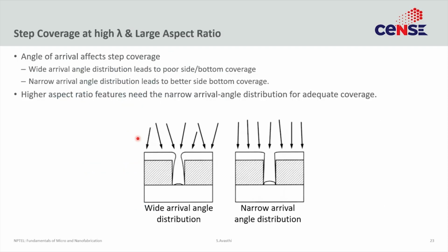Let's talk a little bit about step coverage. We discussed that CVD is often very good at step coverage because it's temperature driven, etc. But here there is no effect of temperature so much. Often the substrate is at room temperature. What you have to be careful about is the direction of the incoming flux.